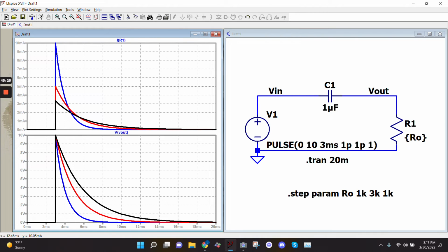Yeah. And that's because in either of those cases, the capacitor's charging. It's just that in this case, this node is not free to move around. It's tied to an input, so it goes 0 to 10. So in order for the capacitor to charge how it wants to charge, this node is the one that has to move like that, right? It's free to move because it's just floating over here on the right-hand side. It's not tied to any source, okay? So that node will discharge, but you would not say in this case that the capacitor is discharging.